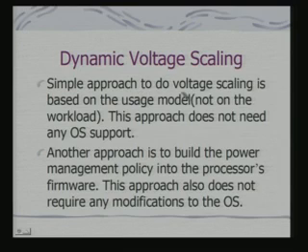So, how to do this voltage scaling? The simple approach to voltage scaling is based on a usage model and may not consider the current workload, and this approach does not need any OS support. This is the simplest way of doing it. Okay. Another approach is to build the power management policy into the processor's firmware itself. This approach also does not require any modification to the OS. So, depending on the kind of usage that is taking place, okay, you switch to different voltages, okay, as part of the firmware specification.